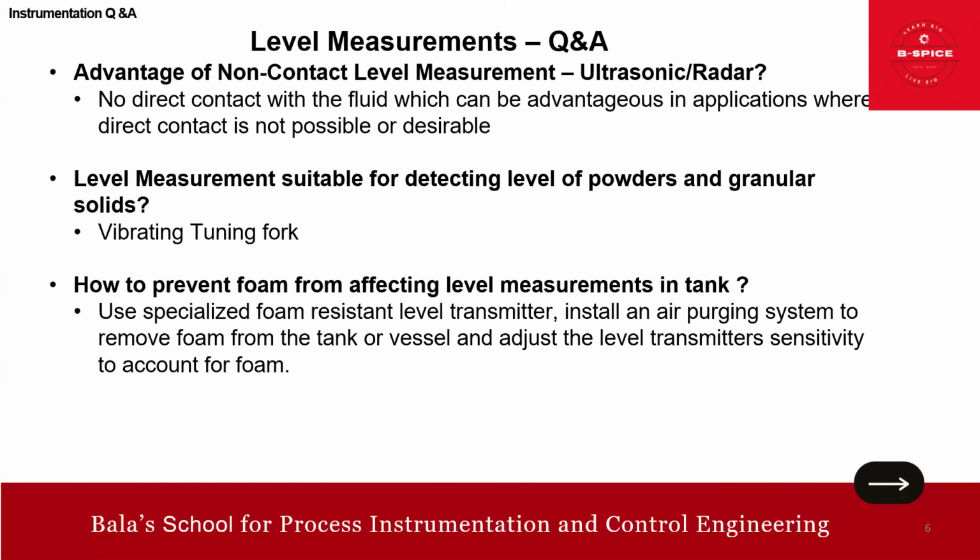And adjust the level transmitter sensitivity to account for the foam. Otherwise, you can mount the transmitter using a stilling well, or maybe you can use the transmitter outside, meaning in a chamber kind of arrangement. You can nullify the foam, yes, to some extent, not fully. But you can use all these measures, right, friends?